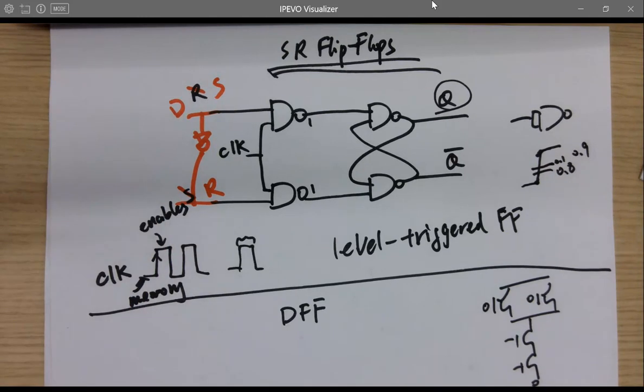And why threshold voltage for PMOS is higher is because holes have a lower mobility compared to electrons. And you use electrons to form the channel for the NMOS, right? And it moves faster, but you are actually forming a channel for PMOS using holes, which moves slower.